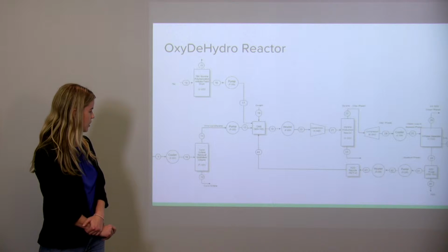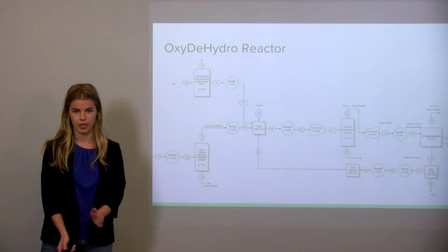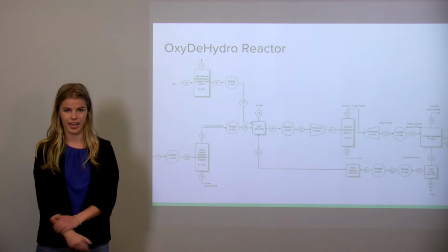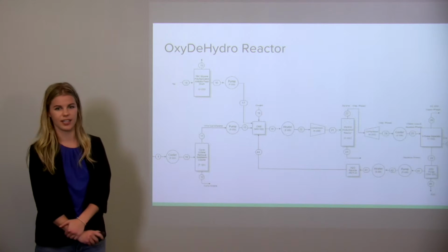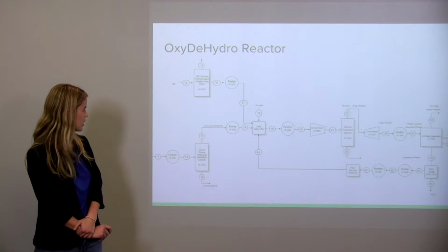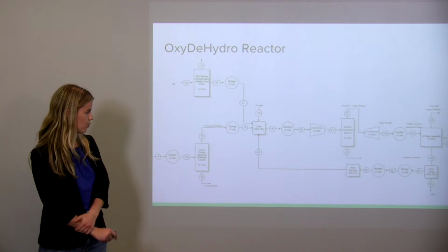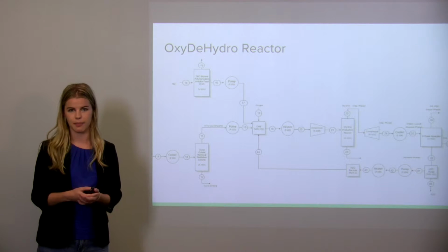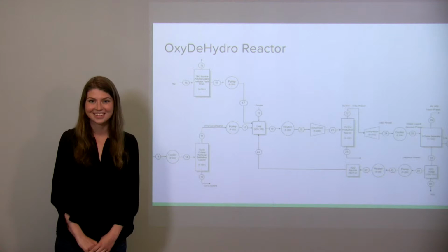So then we continue on with the process, and at this point we want to mix in our inhibitor, which is TCB. The point of the inhibitor is to prevent styrene from being polymerized. So right now it's in a storage tank up here, just at standard operating pressure and temperature. Comes down, we mix it with oxygen as well as the recycles, and then it goes through a heater and a compressor in order to make it into the appropriate temperature vapor phase to go into the reactor.